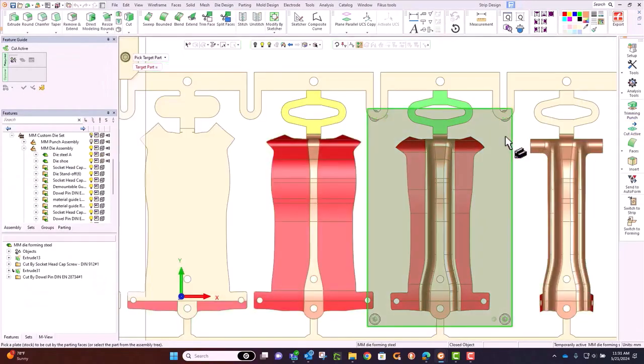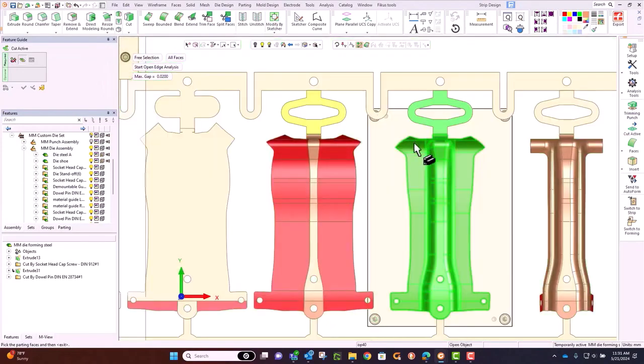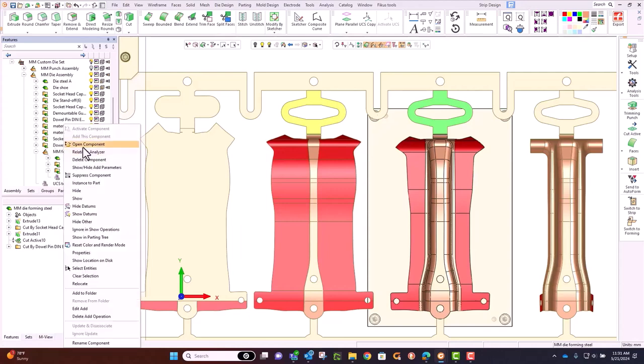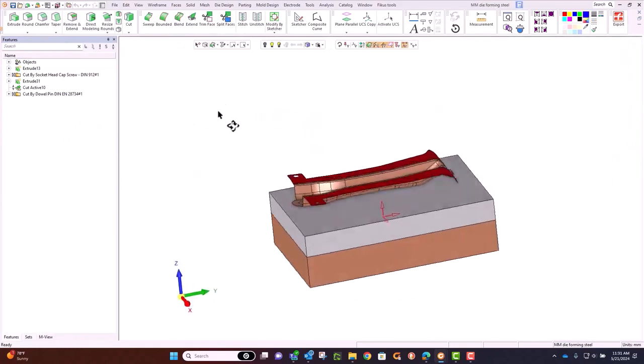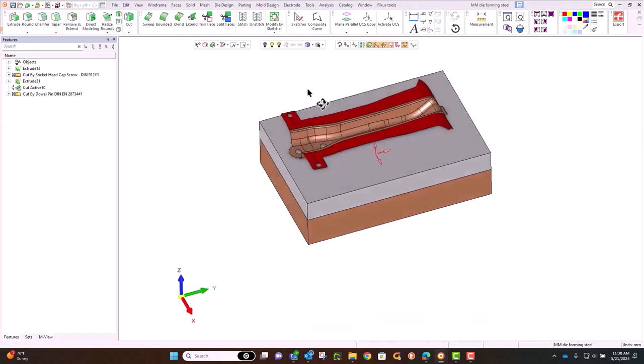I'm going to now say I want you to work with that particular station or operation. So it brings in that part that had the 2 flanges. Here I did a quick little operation so I can look just at the parts I'm working with. The brown bottom you see is the part of the die steel that sized itself to match what was in the die set, and then the gray, that's going to be the area that I manipulate so that I can capture the geometry of this particular station.